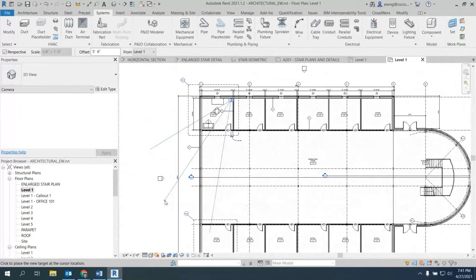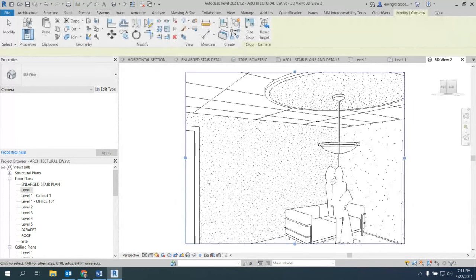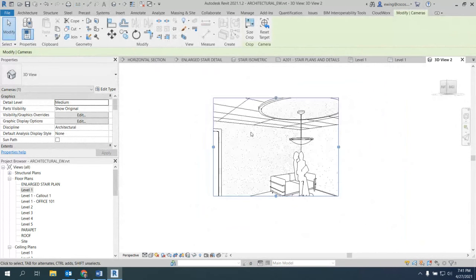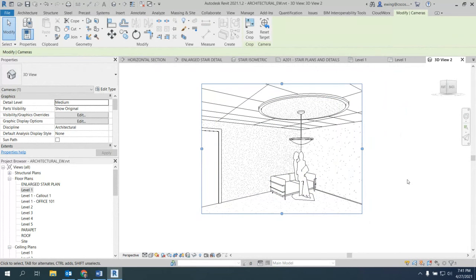We're going to beam it on Cynthia here, but go way past it. The farther you go, the wider the perspective is going to be. So we'll pick a point right about here. Once that's open, we can widen our little box just by grabbing those grips. Oh, that looks nice. Now we can set our visual style to realistic. And it takes a second.